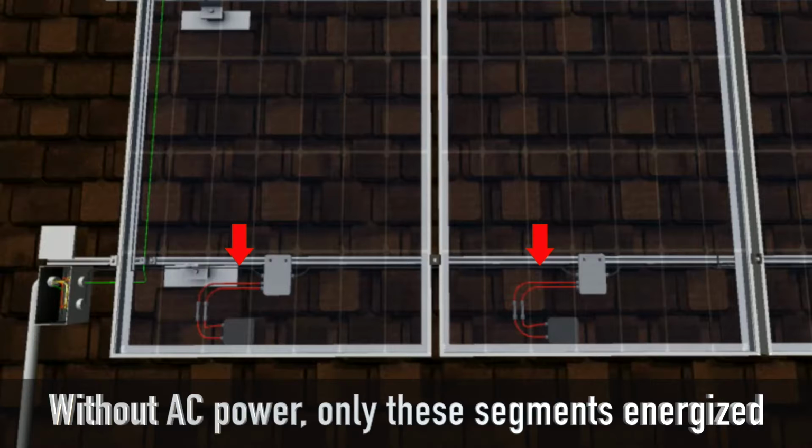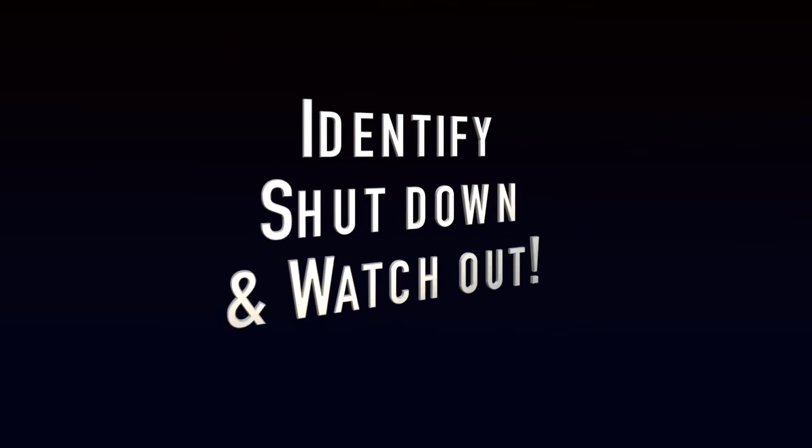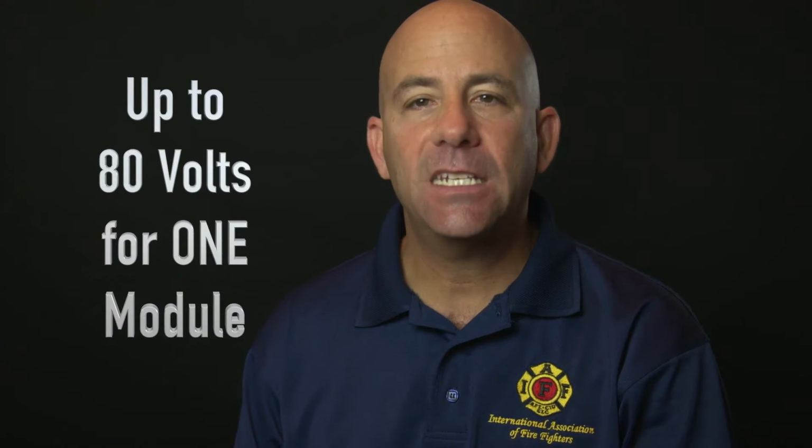As an example, on a typical residential string installation, it could be operating at between 300 and 600 volts when the power is shut off to the building and the inverters are off. With a microinverter installation, there would be no more voltage than from a single module present when the power is shut off. However, in very cold conditions, the voltage can go up. So there would be a maximum of 80 volts present just for one module. Again, it's not in series, so it's not going to increase. So maximum of 80 volts.